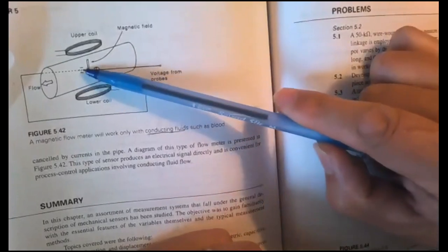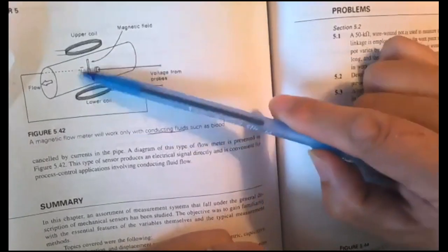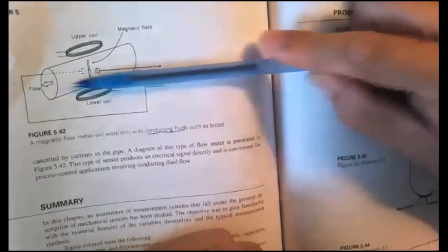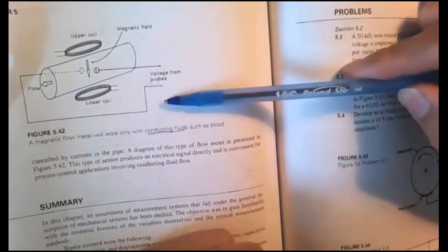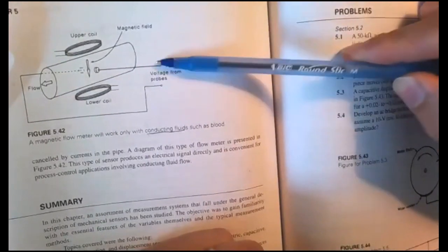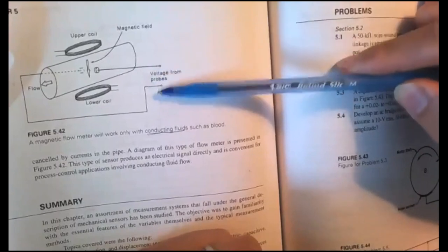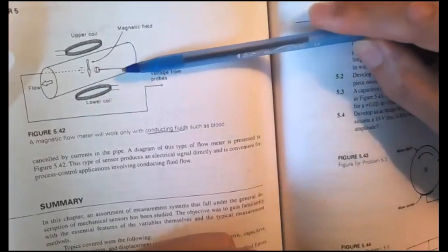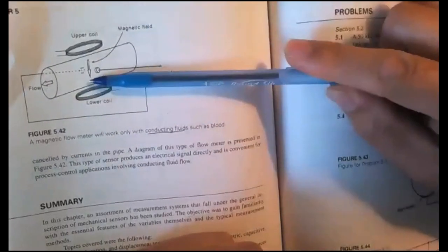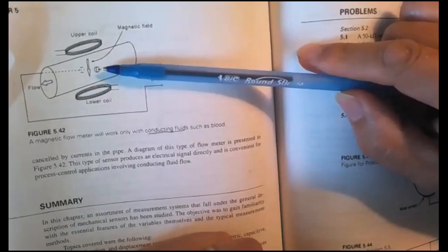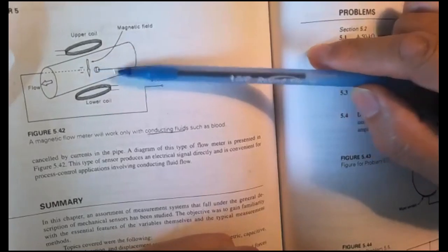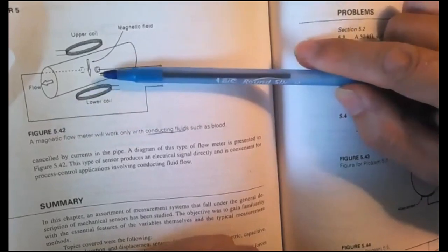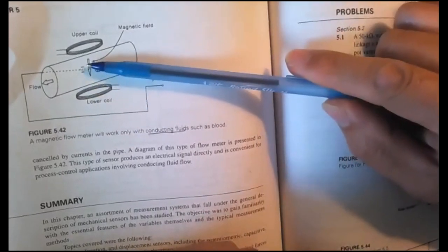So we can have two electrodes attached to the left and right. And the faster the dirty water travels, the higher the voltage it will generate. So we will have electrical circuits to measure the voltage. By measuring the voltage, we can have an idea how fast the water flows. This type of sensor only works for dirty waters. If the water is pure water, drinking water, it doesn't work. Why? Because there's no electrolytes.